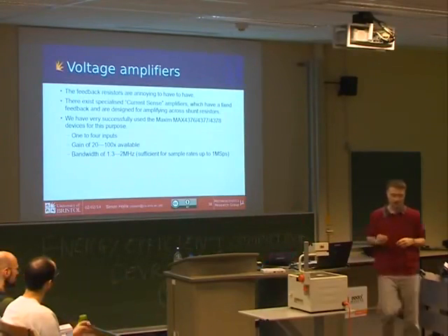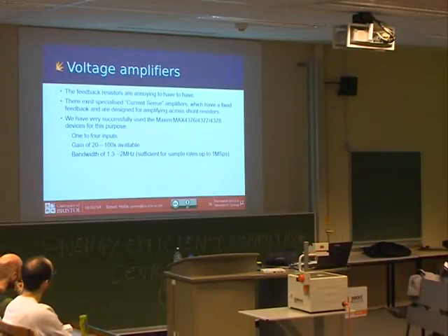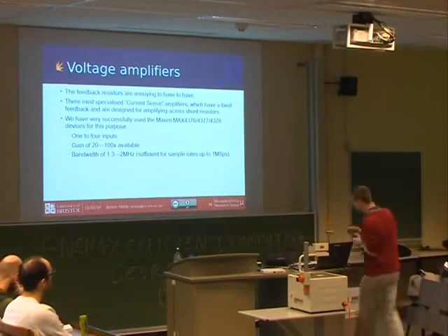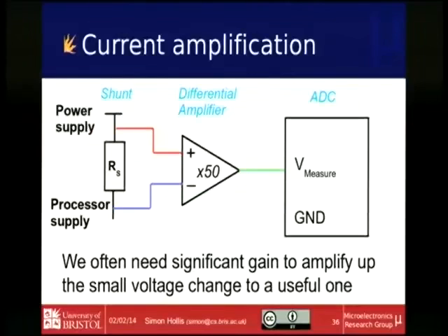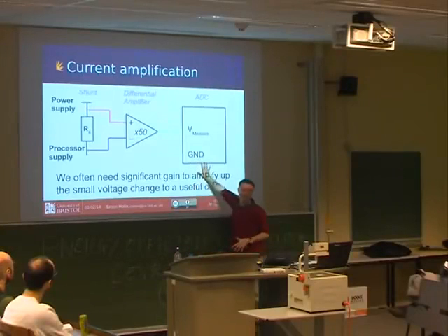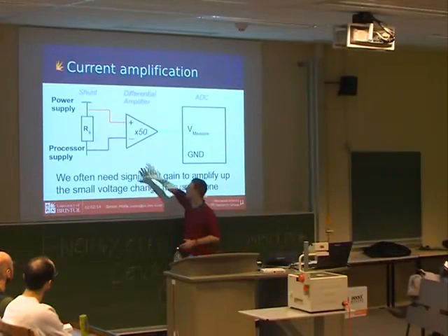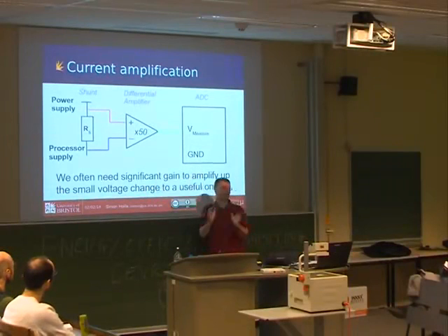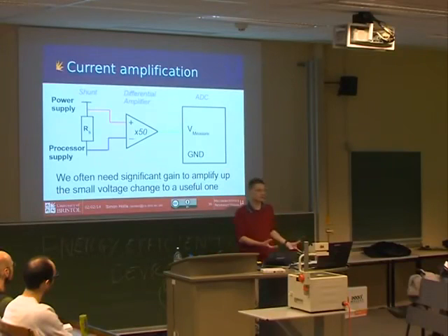There's no point in that? There's not quite no point, there's little point in that, because what you've done is you've created a system where, go back to this diagram. So you've got a system here. If this can measure very, very quickly, you've introduced in the middle a weak link. Okay. Yeah. So this passes all of the information from the resistor into the ADC because it has this limit. And so the ADC can go faster and faster and faster. There's no more information to be got.